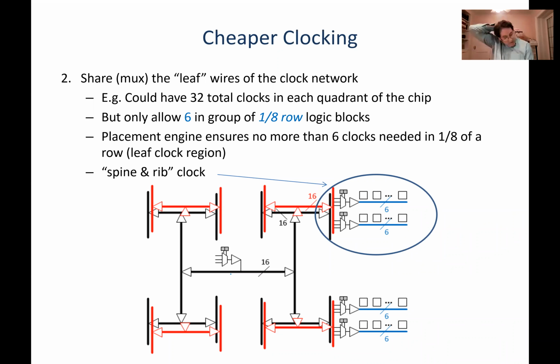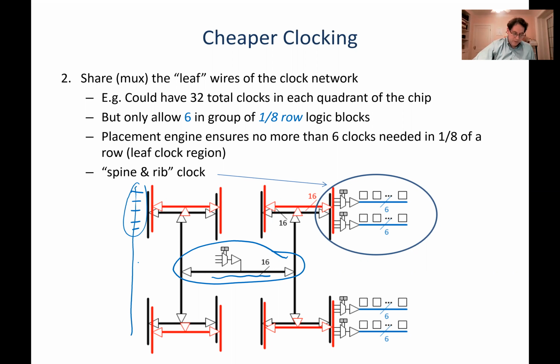And we can. So a common technique here is the top part of a clock tree is not that expensive, right? So this is 16 clock trees, but let's just pick one of them. That's one wire, okay? It's a pretty long wire, spans half the chip, but it's just one wire per clock network. By the time I get to the end of the H tree, I'm going to have one wire in every single routing channel. So if I looked across the chip, I would find that there are a lot of wires to finish off the last little bit, the leaf nodes of each one of my H trees. So that's where things get really expensive.